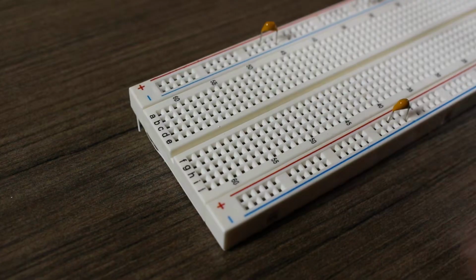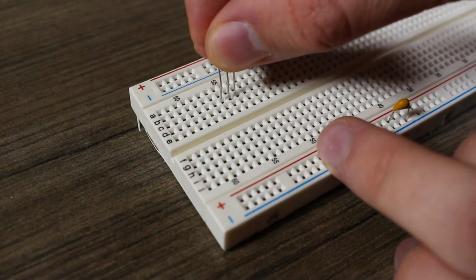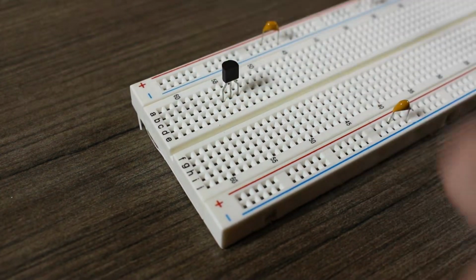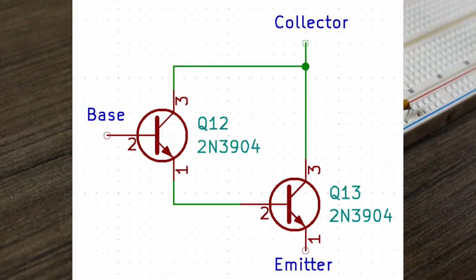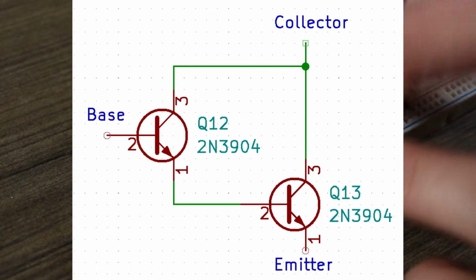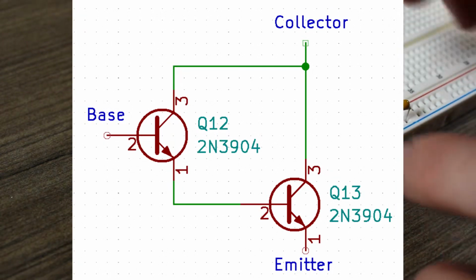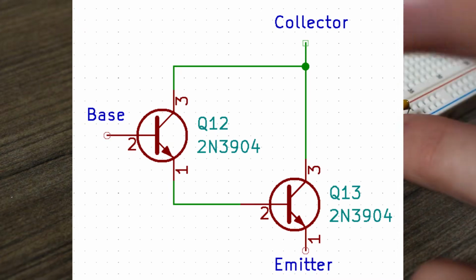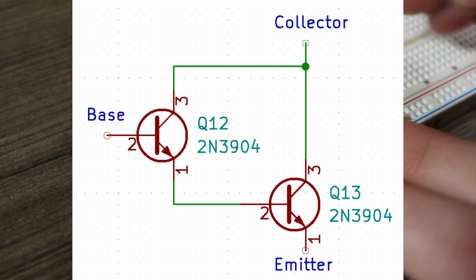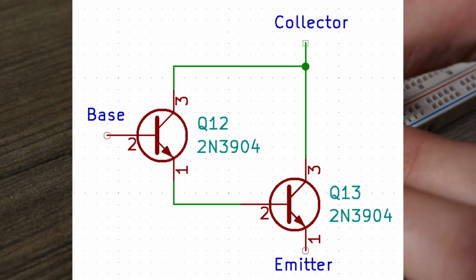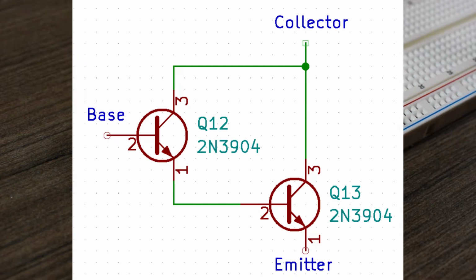You may eventually come to a point where you need more gain from your transistor. In that case, you should take a look at the Darlington transistor. It's simply made up of 2 single transistors of the same type together in order to form one larger virtual transistor. What happens here is that we essentially have a BJT that drives the next BJT.